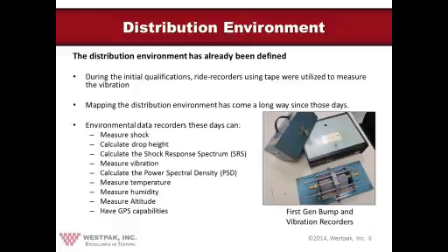Well, sort of. The one right underneath it is a B&K bump recorder, and we actually did use that. I think it's still around here someplace. It had 18 D-cell batteries in it. As you can imagine, stacking those things up inside of something, it was heavy. It actually had an accelerometer, and it would record in 3 axes. And it would give you both acceleration and velocity change, and if you did your homework exactly right, you might be able to convert that information to drop height. It couldn't record vibration, but occasionally it could give you an idea of the drop height.